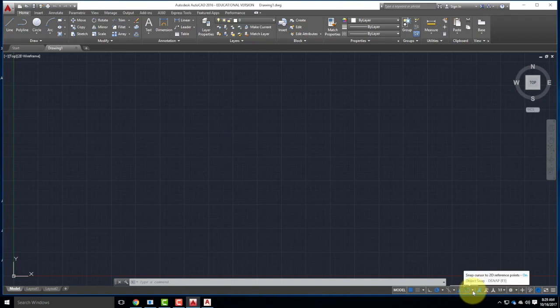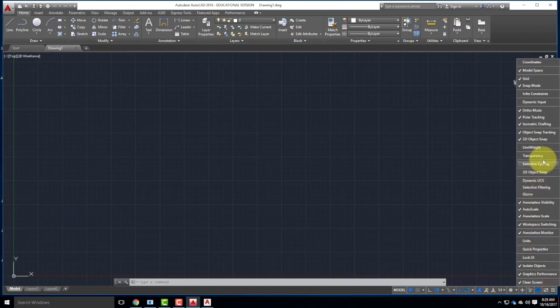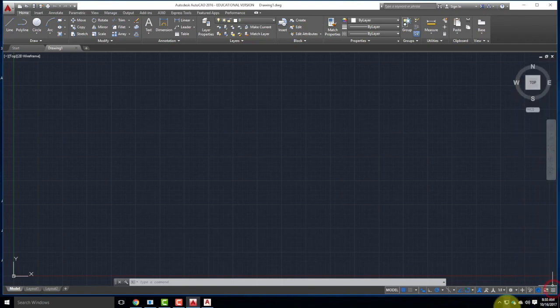I do need you to turn off, as we get started, something called Dynamic Input. And it's not shown by default in your AutoCAD. So I want you to go to the 3 little lines in the far right corner. And I want you to check the box for Dynamic Input. Okay, so that dynamic input should be checked. And once you've checked that, dynamic input should look like a little plus with a box below it. So I'll draw that here. I know these are at the bottom of the projector. Should look like a plus with a little filled in box below it.